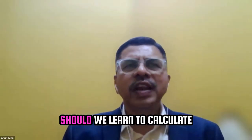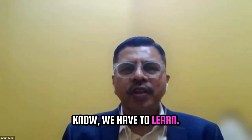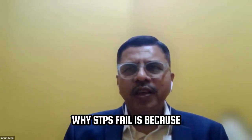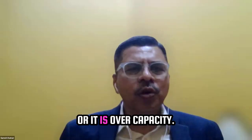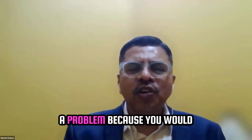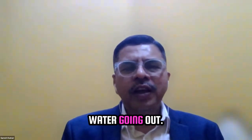First question: why should we learn to calculate? One of the major reasons why STPs fail is because they are either under capacity or over capacity. Both are a problem. Under capacity is a problem because you would have a risk of flooding and untreated water going out.